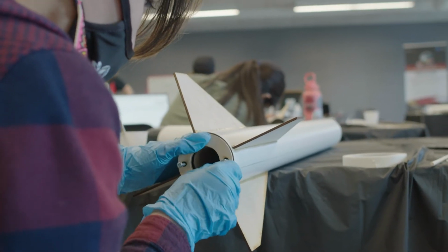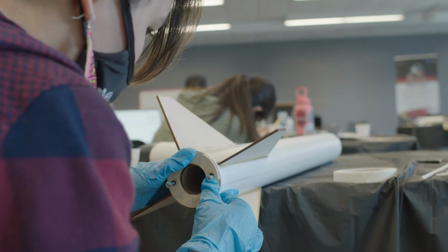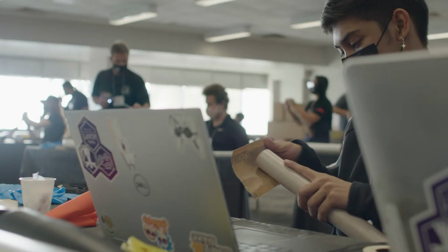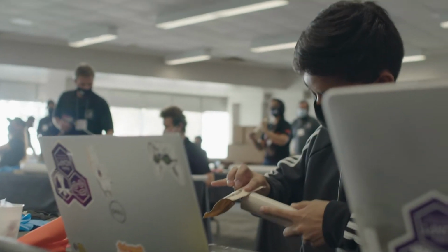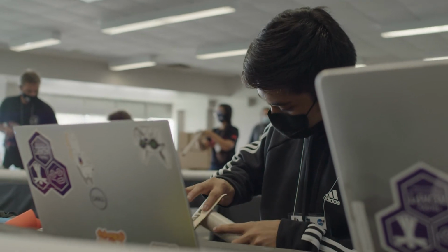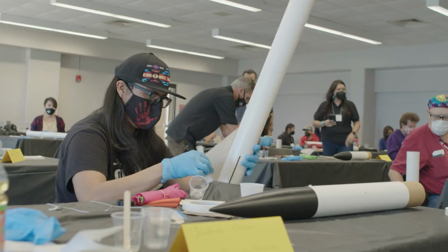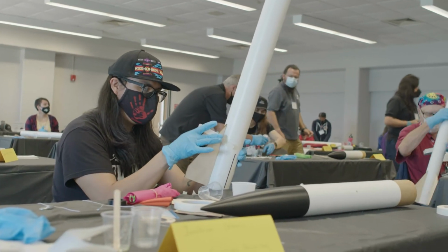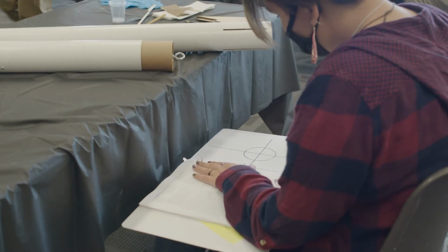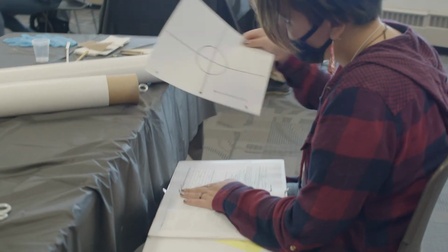A fundamental rule of adhesives is that more surface contact area creates stronger bonded joints. For example, sanding a surface before gluing cuts micro-ridges into the surface, creating more surface area and a better bond. With most adhesives, maximum bond strength is not produced instantly. The assembled joint must be supported in position while the adhesive is curing. Plan ahead how you will keep parts aligned while your adhesive cures.